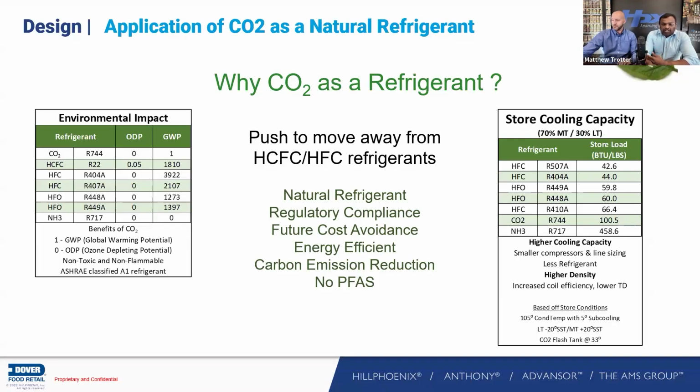It helps in reducing carbon emissions, and also it has no PFAS. PFAS is the talk of the town in many places, and in Europe there is a ban on PFAS. So for CO2, there is no issue or concern about PFAS. That's why CO2 is a good refrigerant to go with as a future-proof solution for the retail industry